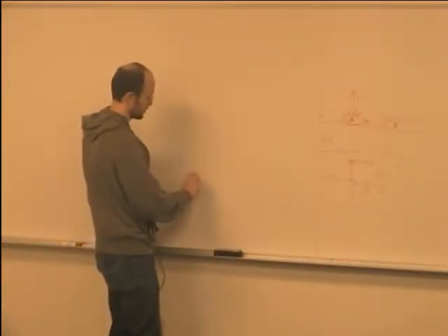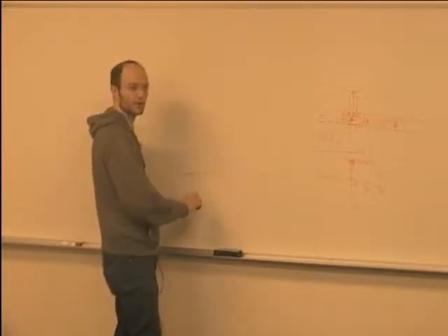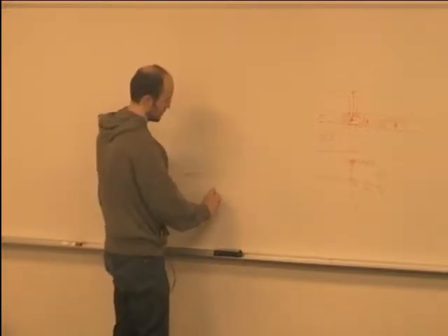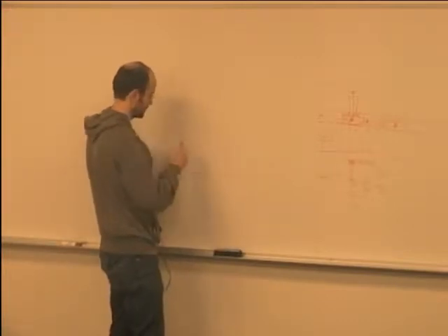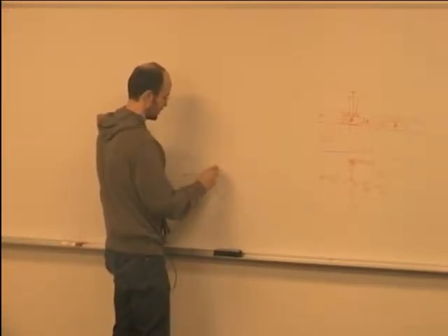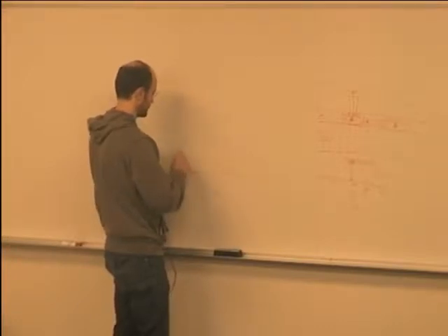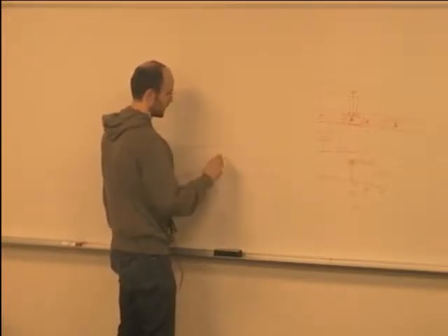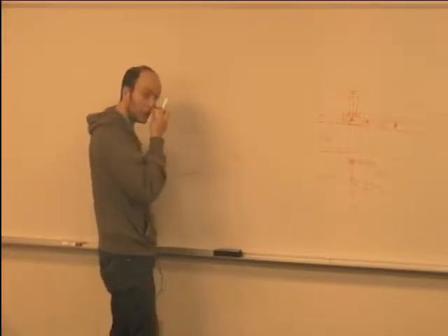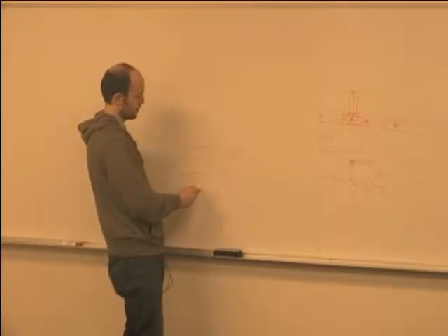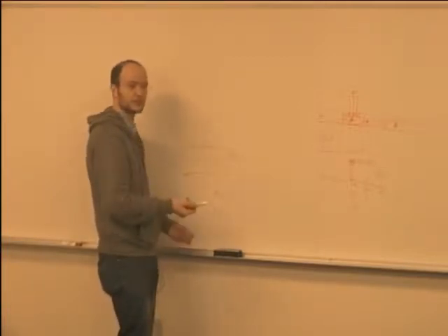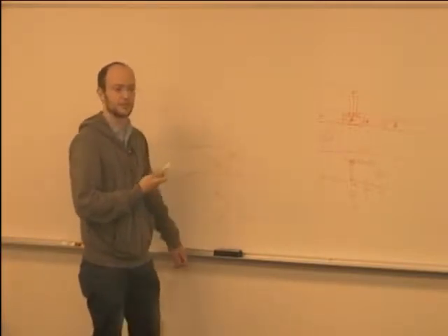So let's try to draw the cross section. This will be diffusion, okay? This will be P sub, which is grounded. Then you have SiO2. Okay, and then let's say that we even have metal 1, okay? So the diffusion is closer to ground, to the substrate, than the wire, okay?